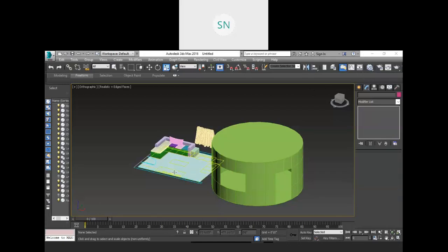Same thing that we have done for the interior, you have to do that for the exterior model. Just bring your AutoCAD drawing, whatever shapes on your exterior wall face, just create that sketch and extrude it and place it over there. Same method we have. But in your exterior, you will not have this curtain system. Rest of all the things are there. You can use extrude, you can use lathe tool, right?